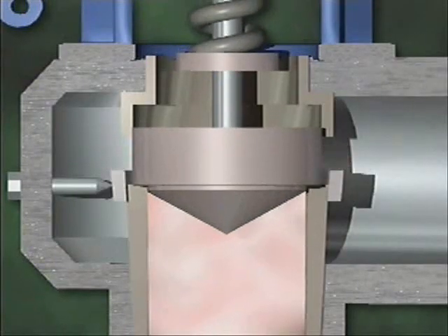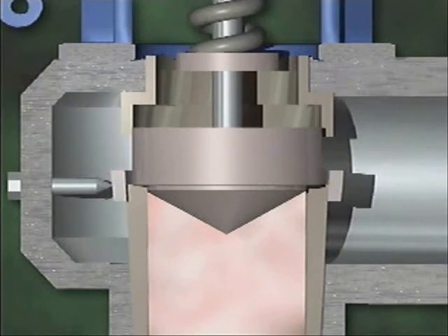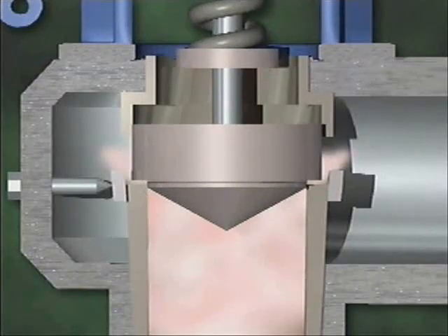Adequate blowdown helps prevent a condition called chattering. You see, if there's no difference between a valve's popping pressure and its seating pressure, the valve disc will jump up and down on its seat until pressure either increases enough to pop the valve open again or decreases enough to keep it closed. This condition is called chattering because of the sound that the disc makes as it moves